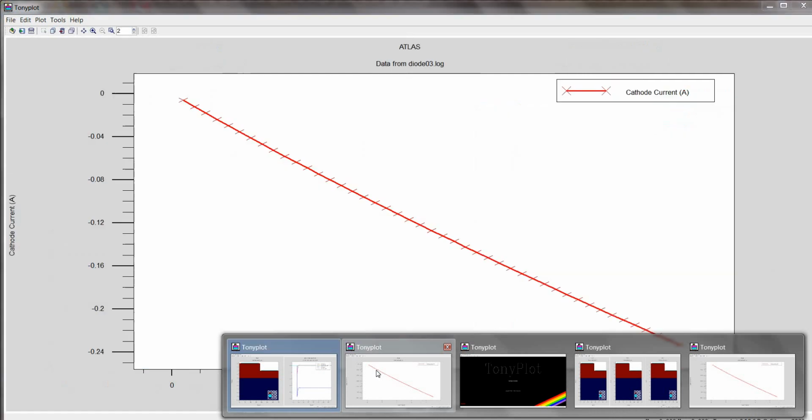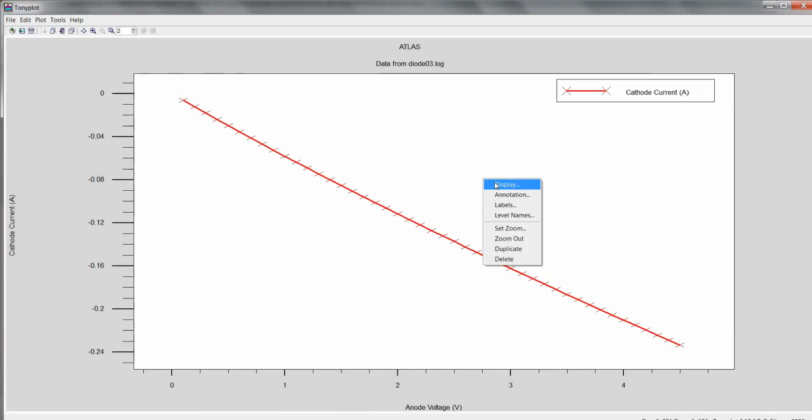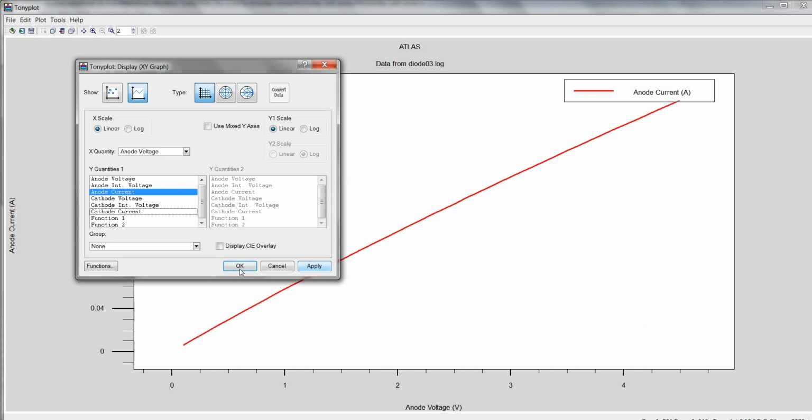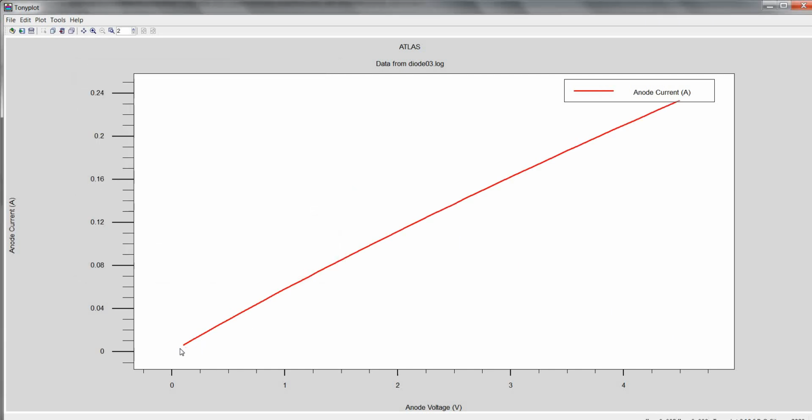So in this case, we call it a non-rectifying barrier because carriers can flow in both directions, and this is also obvious from the current voltage characteristics of this structure under forward bias, where you see a linear relationship between the anode current and the anode voltage as compared to the Schottky diode, in which we have a turn-on voltage. So in this case, we see a linear behavior of the current versus voltage, and that also signifies its non-rectifying behavior.